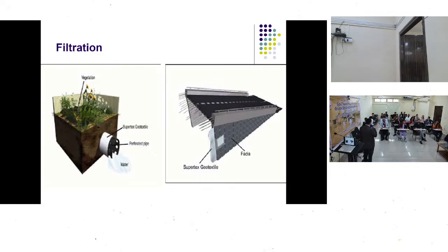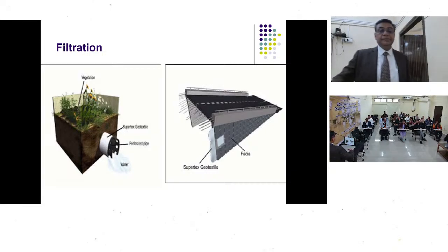Again, the concept is the same: it will allow only the water to flow through and not the soil particles. At the bottom I can have a drain, wherein all the water draining out in both directions is collected and then passes through the main drain and goes out. That is how I can plan for a relatively much more stable embankment or fill.